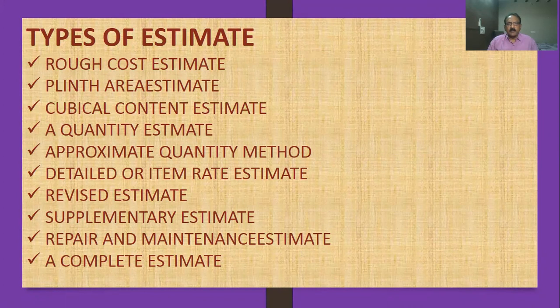Revised estimate. Sometimes, even though we have given abstract estimate, suddenly there is a rise in the cement bags. Within 1 month, what will happen? It may increase 100 rupees. Then revised estimate is required. Similarly, suppose reinforcement, reinforcement also varies with the time.